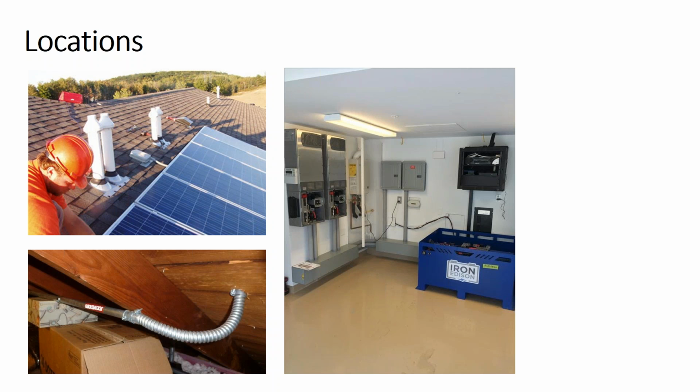So let's look at some a little more technical things about these environments. We talked about temperature sizing, and so now what we see in this picture is that we're in the attic here, and then we're going up into a roof-mounted junction box. And so you might ask yourself, well, this is a wet environment, this is a dry environment. Inside the conduit itself, where does the environment magically change from a wet environment to a dry environment? Is it a dry environment inside the first box that you land on? Is it a dry environment inside this conduit?